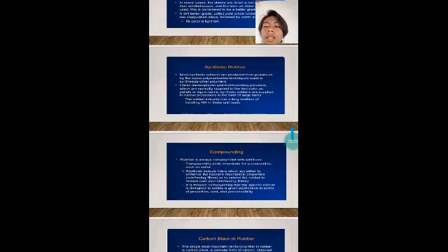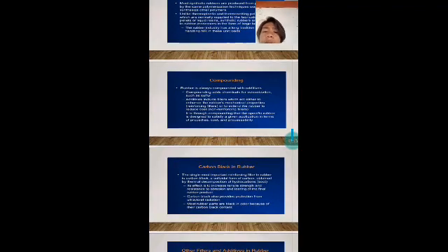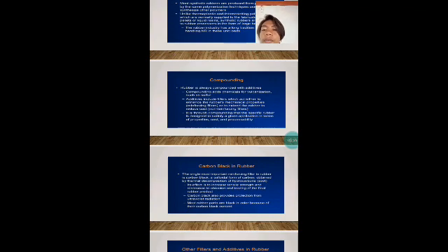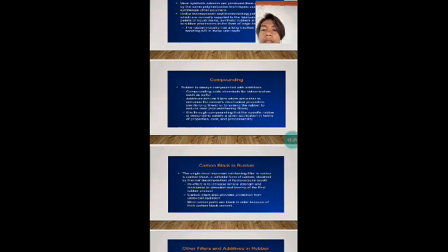So next is compounding. Rubber is always compounded with additives. Compounding adds chemicals for vulcanization, such as sulfur. Additives include fillers, which act either to enhance the rubber's mechanical properties, reinforcing fillers, or to extend the rubber to reduce cost, non-reinforcing fillers. It is through compounding that the specific rubber is designed to satisfy a given application in terms of properties, cost, and processability.